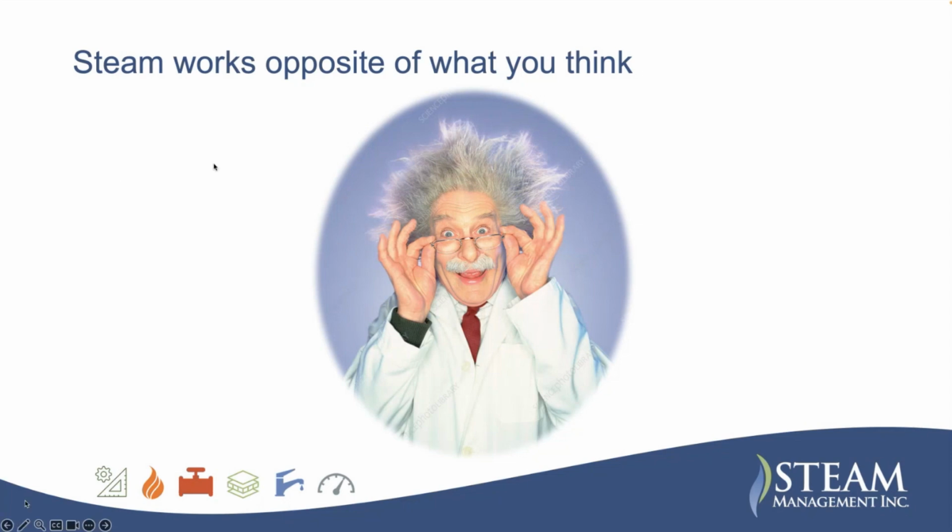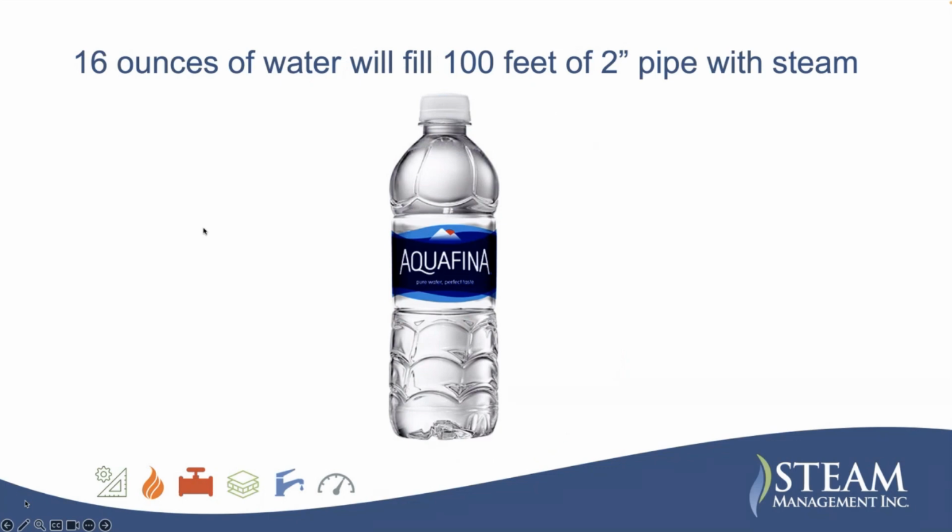Steam works opposite of what you think. So if you're in a steam system, you've got to throw away all your HVAC expertise and your hydronic expertise, because it goes opposite of everything you're thinking of. When water turns to steam, it expands at 1,600 times its volume. To put this into perspective, we have a 16-ounce bottle of Aquafina. If we were to turn it into steam, it would fill 100 feet of 2-inch pipe.